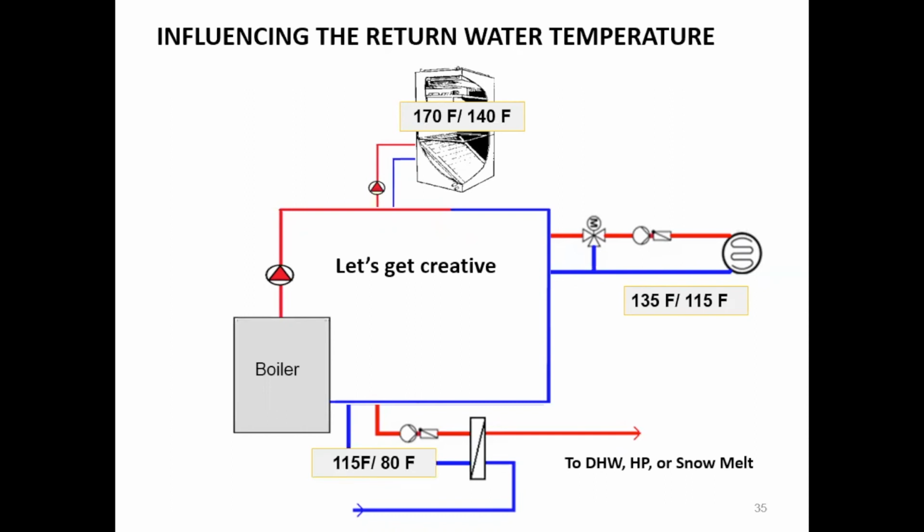So all of a sudden the water goes out there. Any one individual heat emitter may only have a 20, a 25, or a 30 degree delta T, but when I start adding these delta T's together, all of a sudden I can open it up to a 50 or a 60 or an 80. We have seen a number of these projects being done.